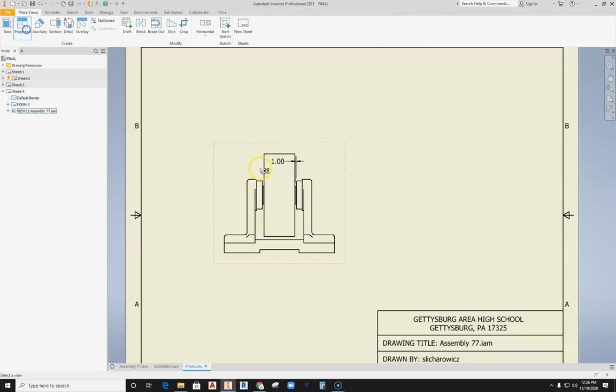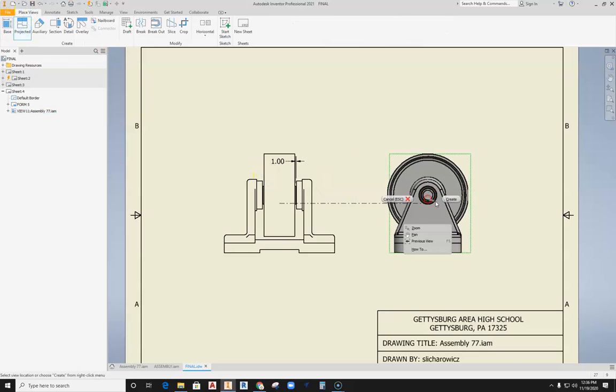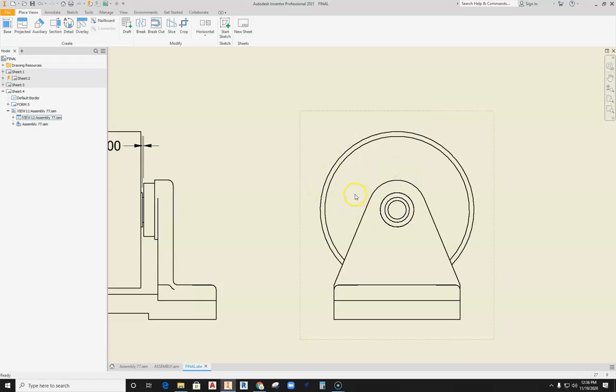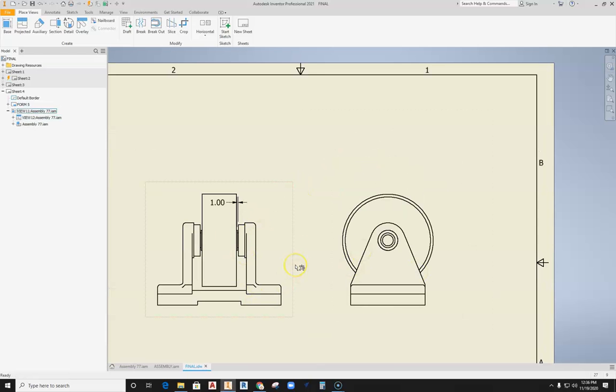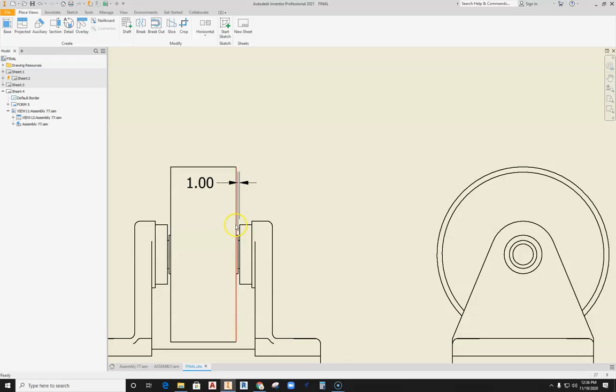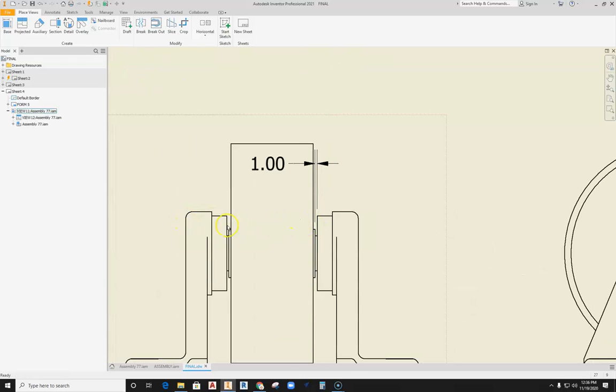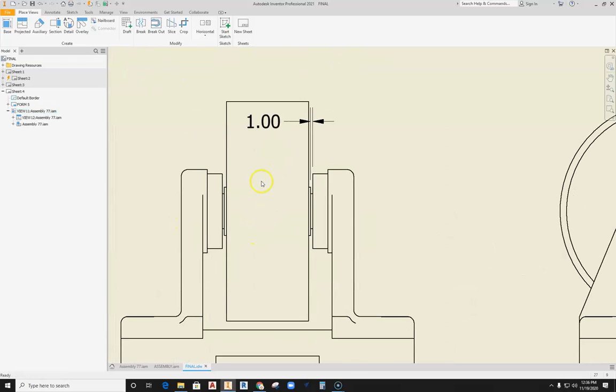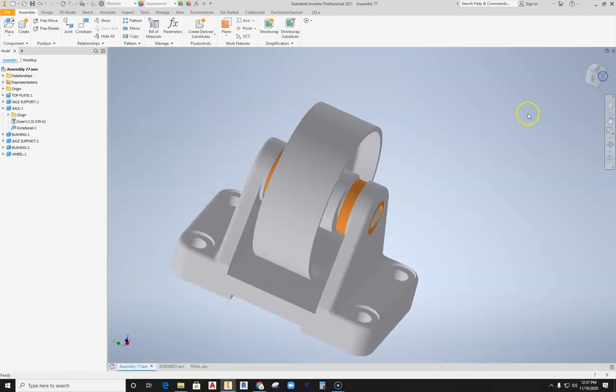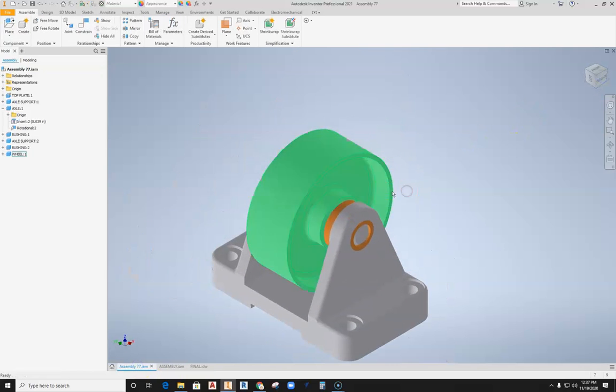So the nice thing, and I do this all the time, is I'm building. I may build, but I will also build with an active drawing sheet model open, because then I can go in and get real-time information on my part. If I realize that, hey, something's not right here, I can go grab a measurement that I know is incredibly accurate, and then I can come back to my model and do the offsets necessary to make it work.